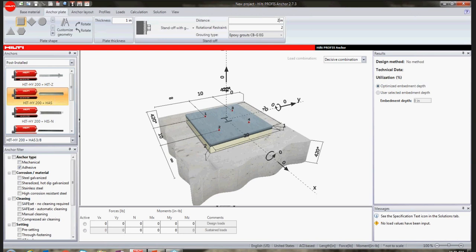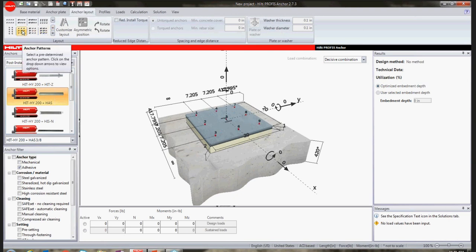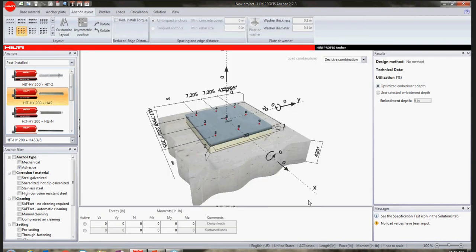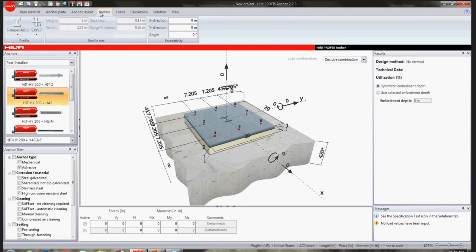So Chapter 17, Section 5 is where these concrete breakout in shear calculation provisions are. It's telling you what equation it is and where it comes from. It tells you the variables that it's using, as well as the calculation. A big part when we're doing concrete breakout calculations with anchor groups is going to be that projected area. So we want to verify that we have calculated by hand ourselves against what the software has calculated for these projected areas, as well as what the software is taking into consideration for our nominal breakout strengths. Again, you're seeing these phi factors, you're seeing where this information comes from.